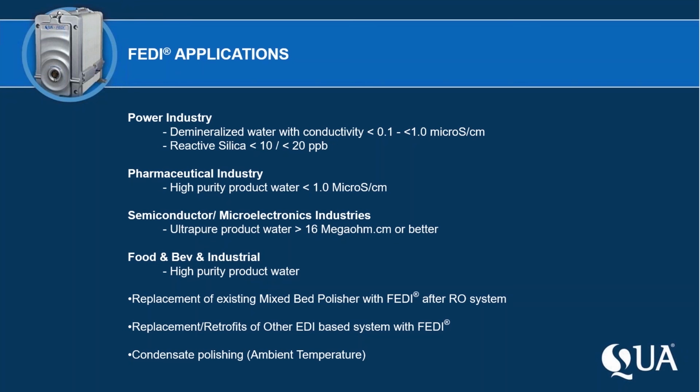The food and beverage industry uses high purity water. They use it for rinsing of tanks. They use it for diluting food products and beverage products. So the use of high purity water is well known, and the Fedi technology fits all these EDI applications. It definitely can replace mixed bed polishing after RO.